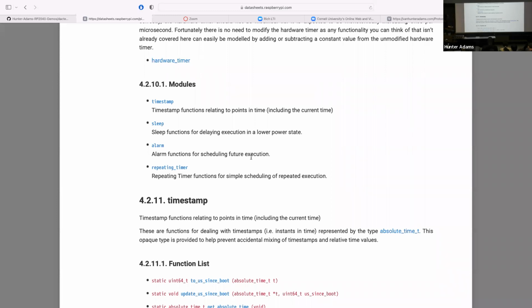You configure it such that when there is a rising edge on one of the pins in that bank, the interrupt associated with that GPIO bank fires. And then if you want to take different actions based on which particular GPIO port fired, it's up to you to then, in that interrupt service routine, read in the value of the GPIO ports, see which is the one that either went high or went low or toggled or whatever it was, and then call the associated callback function for that particular pin.